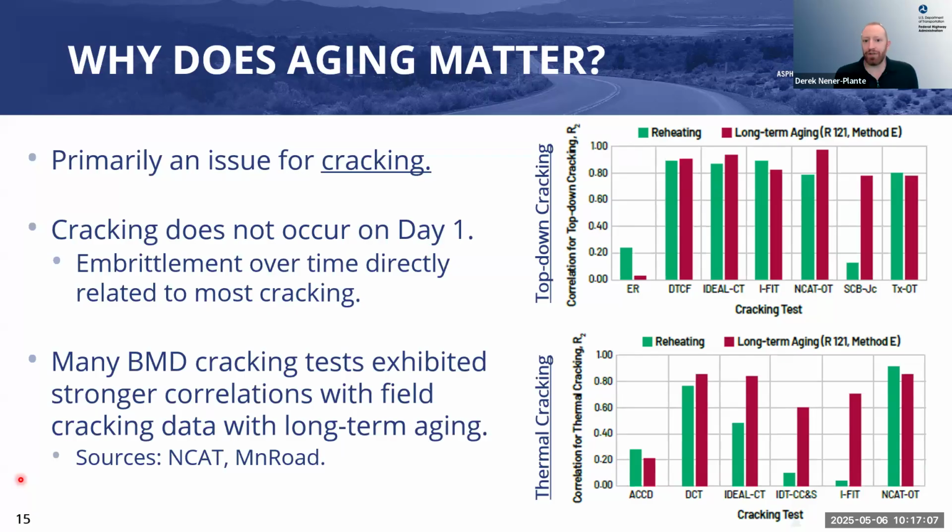If we think back to our entry-level schooling when it came to asphalt mixtures, we need flexibility for this asphalt mixture to retain its resistance against cracking. And we're not worried about that on day one. We're hopefully not. But we have an asphalt mixture that, when exposed to the elements, weathers, oxidizes, and embrittles over time. With repeated loads, exposure to the environment and thermal stresses, the material itself is embrittling, therefore making it more susceptible to cracking in general.